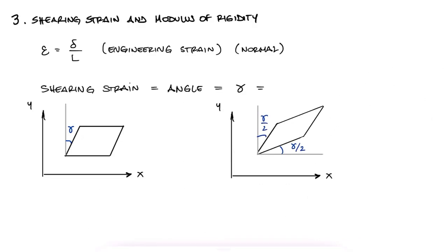The notation we use for shearing stresses has sub-indices that correspond to the face and direction the vectors affect. For example, on the y face or top face, there is a vector facing in the x direction, and therefore the shearing stress is tau yx on the top and tau xy on the side. And of course, for this element to not be rotating, these two values are the same. By convention, we say that a shearing stress is positive if both vectors are pointing towards the positive directions of the axes, which is usually the top right corner for standard positive directions of x and y.